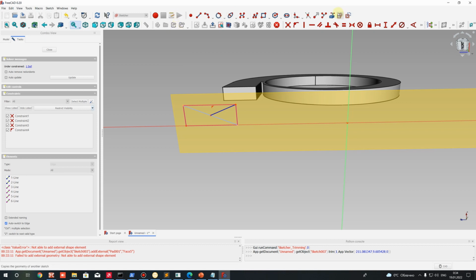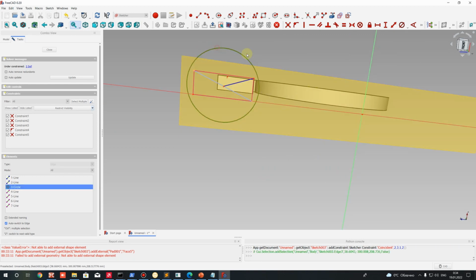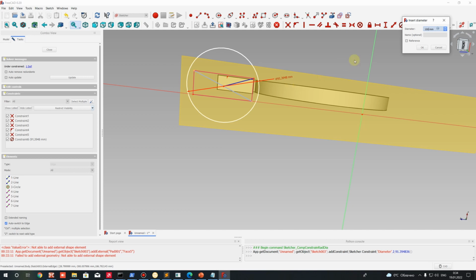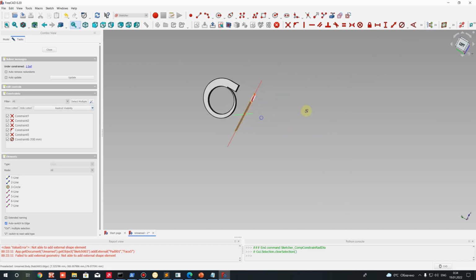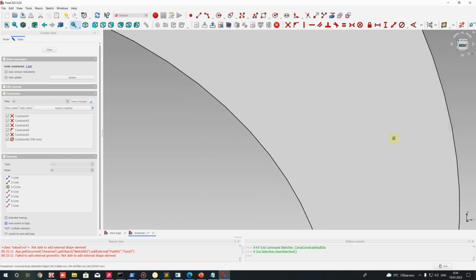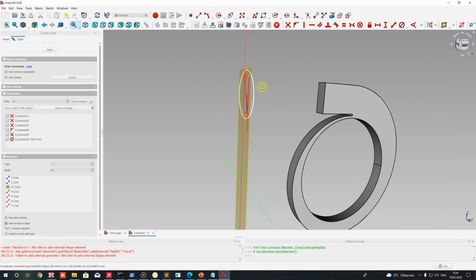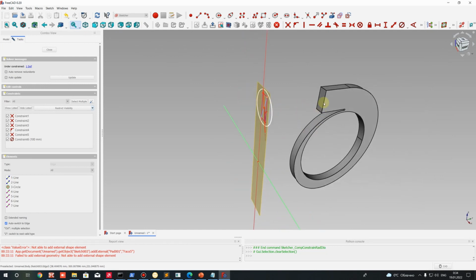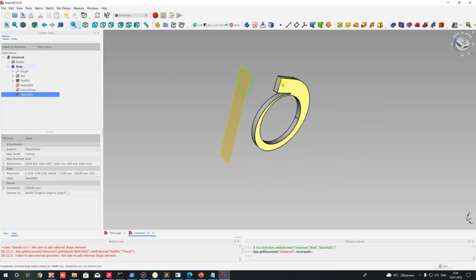Let's change the mode of working for your toggle construction geometry, and let's go to creation of circle here, and let's set here some diameter for your, I think we can use this value for your outlet from your volute. And after that we have to close the sketch, go to this